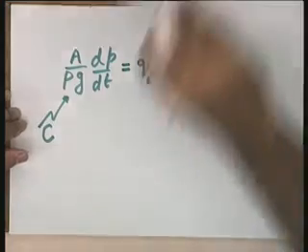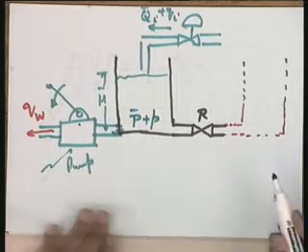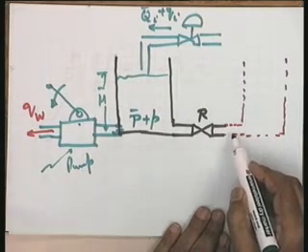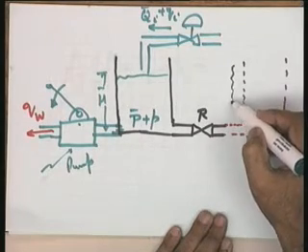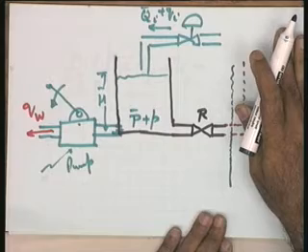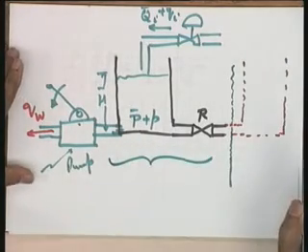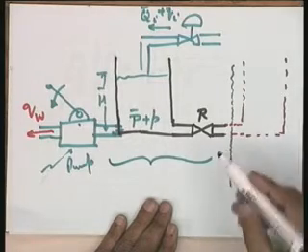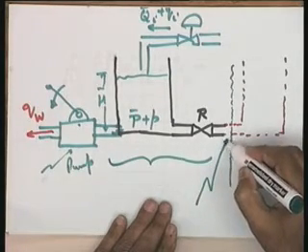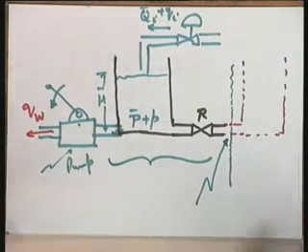You have to help me here. See this variable P bar plus P. What is the situation here? In the earlier case, it was taken as 0 gauge pressure, but now you see, this part of the system is not in your control. You have been assigned the control of this particular tank, and how the other tanks are operating is not in your control. But if there are disturbances in these tanks, in cascades of tanks, there is a possibility that the pressure at this particular point will not remain equal to atmospheric pressure. It will not remain at a constant value.